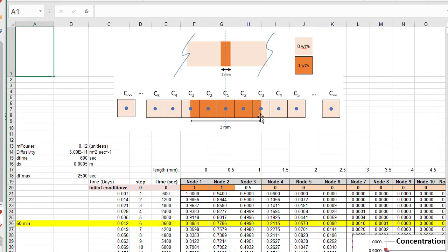Noticing that the volume here is 1/2 and 1/2, when I do my starting conditions, I'm not going to be using 0 and I'm not going to be using 1. It's 50-50, so I'm going to use 0.5 as my starting case. That's my average concentration in this volume, and that node represents the entire volume, so I need that average concentration. And that's what you see here. My node 3 is at 0.5 to start. My node 1 and my node 2 are at 1 to start.